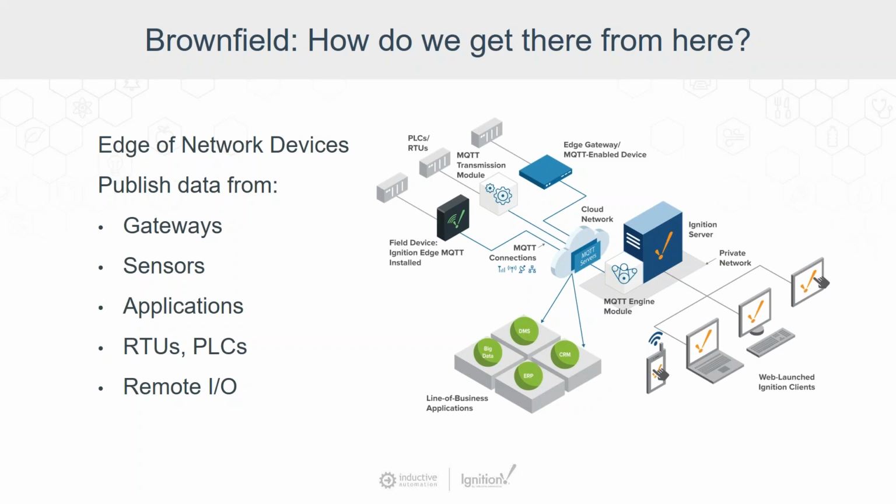It could be on-premise, or of course it could be in the cloud, and we can do that securely. And so the idea is that we can put these edge gateways in front of our PLCs, and we can start doing that slowly to transform our architectures to a more modern architecture, where then we can use modern applications, modern SCADA, to be able to take advantage of it. So that's an important part of MQTT, is once we bring it to that server, there are many applications, from business applications, of course, to SCADA applications that can consume and do a lot of interesting things with that data.